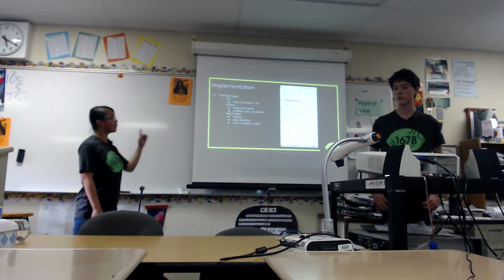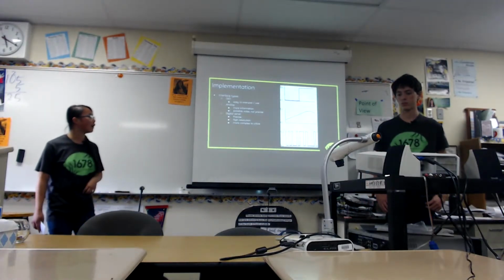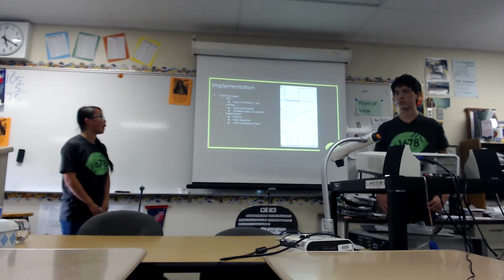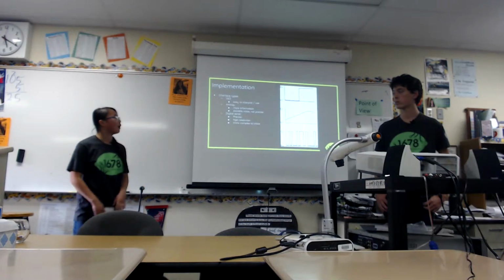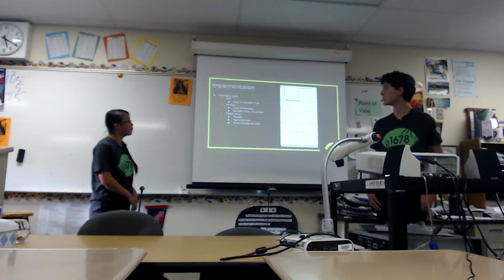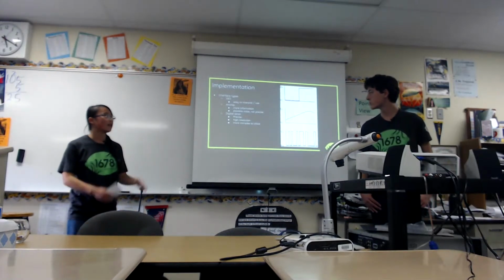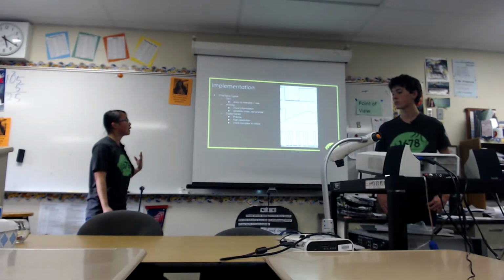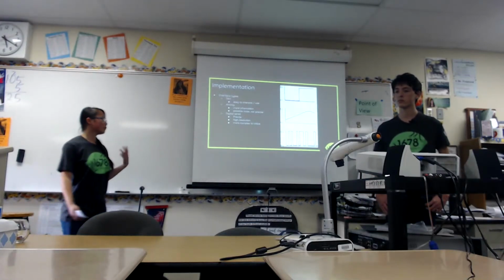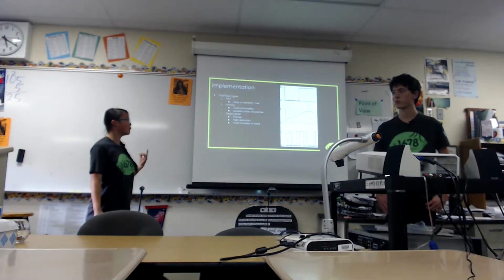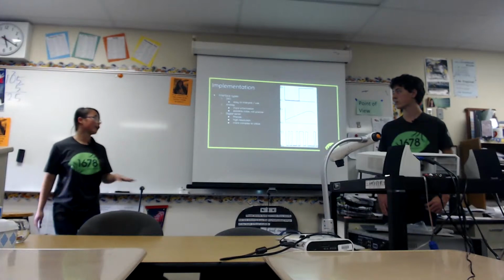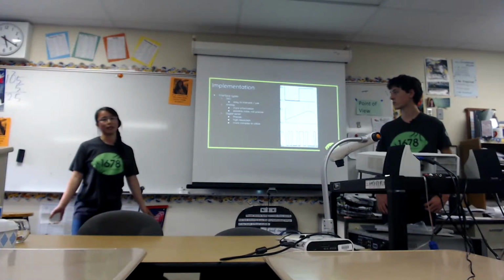So here are different graphs of different types of signal outputs. There's DIO, which is digital input output, which is easy to use, super simple and useful. And then there's analog, which has values between a whole range of values, and it is more susceptible to noise, so it can be not as precise. There's also digital serial, which is precise and high resolution, but it's more complex to use.